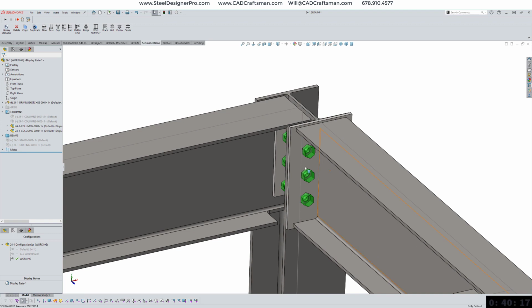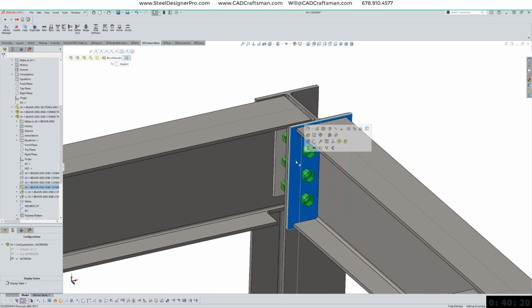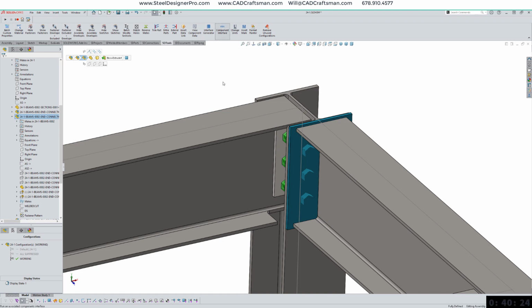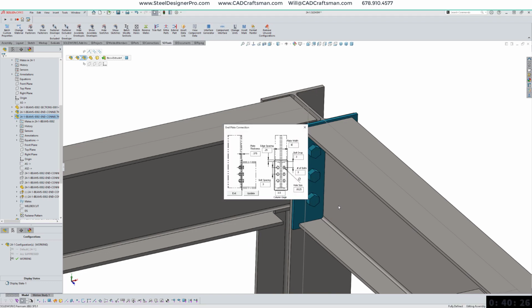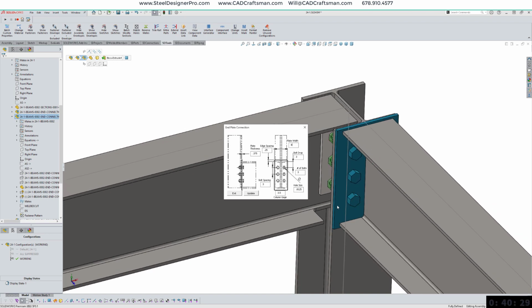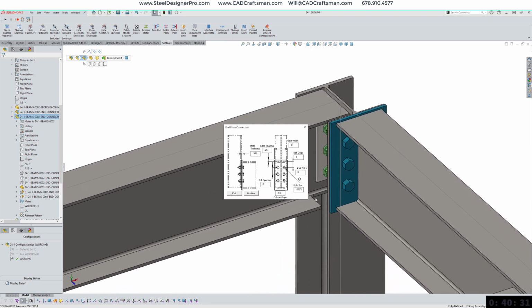Now that the column heights have been adjusted, I need to adjust the two end plate connections. They are a bit too high now. By choosing a negative value for the edge spacing, we leave room for a top weld.